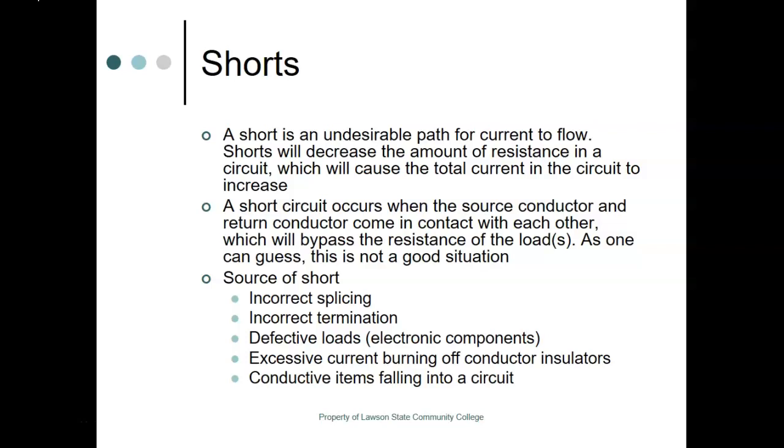No, but seriously, if you put way too many strings of lights on the same cord, it actually will pull enough current that it will catch fire and can burn off the insulation. At which point you're going to end up with an arc over. So, much as you like Christmas cheer, don't bring it down to only one power cord. It's not a good idea.